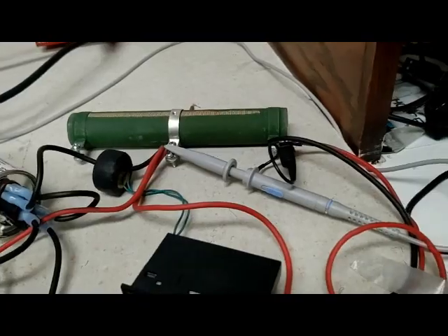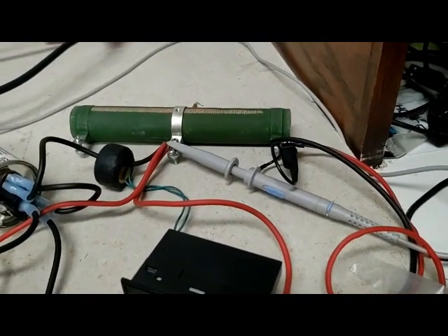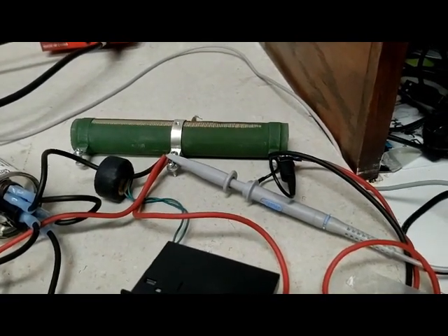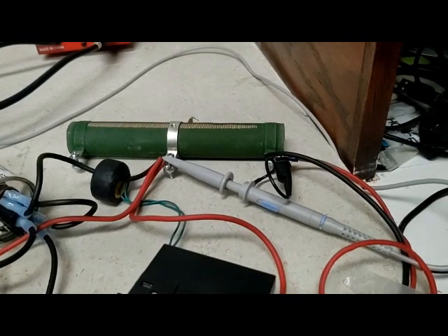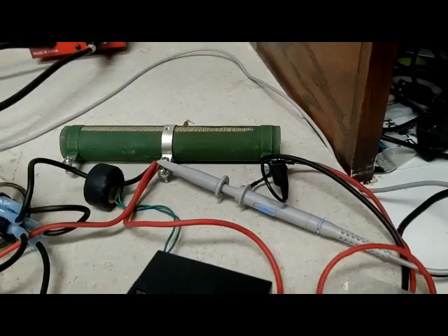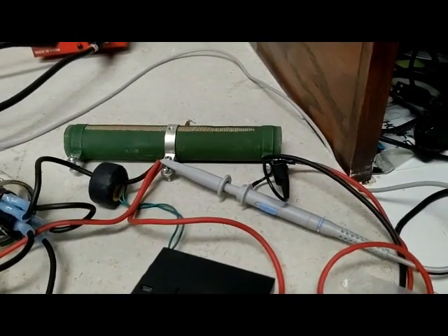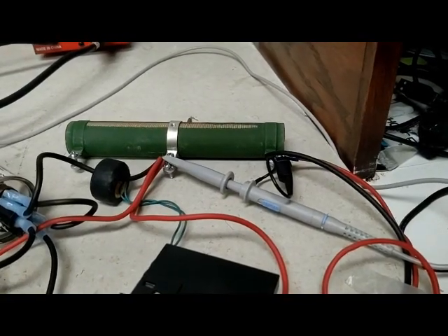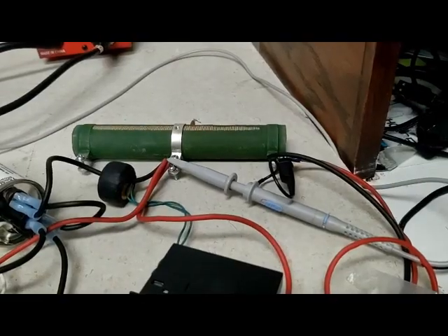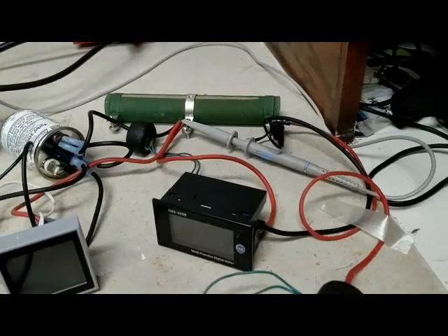Channel 2 of the oscilloscope is checking the voltage across the resistor. Why do I want to check the voltage across the resistor? Well, because the current will always be in phase with the voltage across a resistive load. So by checking the voltage across the resistor, I can also see the phasing of the current in the circuit, and therefore we can see how the inductive and capacitive reactance affect the current versus the overall voltage of the circuit.